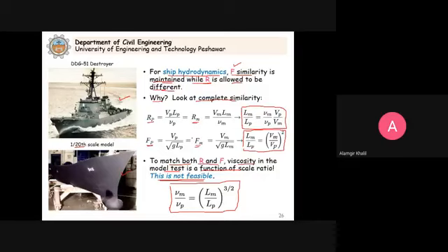That is due to gravity, so we only want to bring in the gravity wave effect. We already studied forces on immersed bodies and how to calculate the skin friction. So from there you calculate and subtract from the total resistance, and we get the wave making resistance of the model.